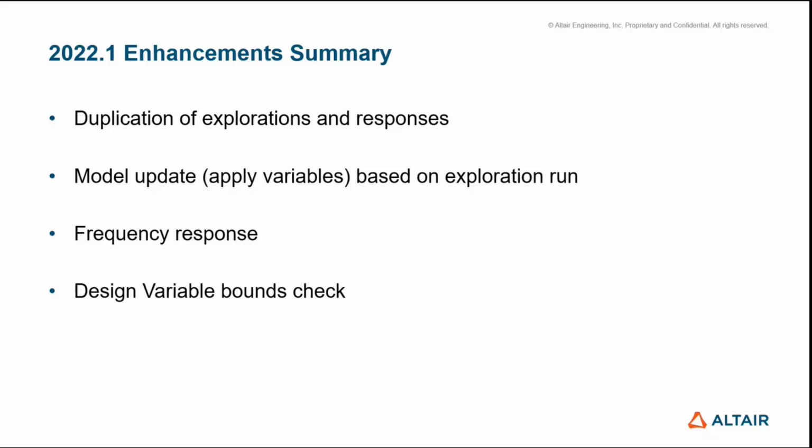I'll show you what that means, but with the parameterization of models in Inspire, if one isn't careful, you can end up defining design variables where, when variables are applied for one run or another, you can end up with some potential issues to your geometry. You can create gaps inadvertently or some part overlaps as geometry moves around. And this is just a tool that helps you to check and catch some of that up front.